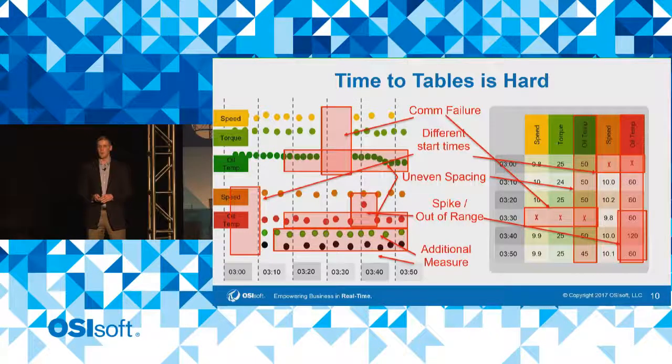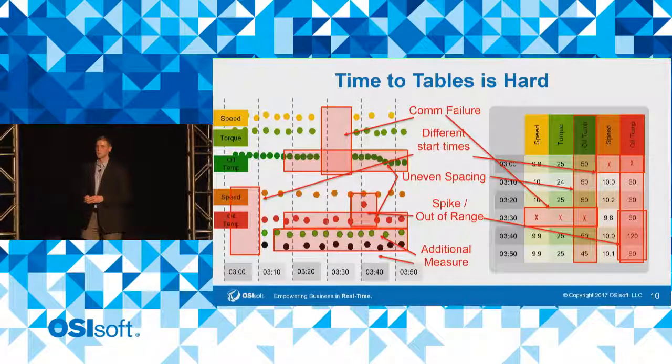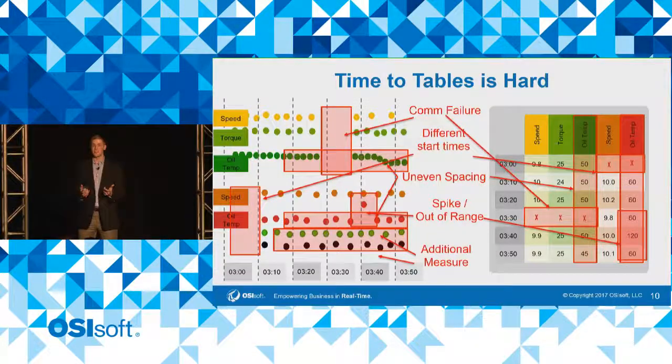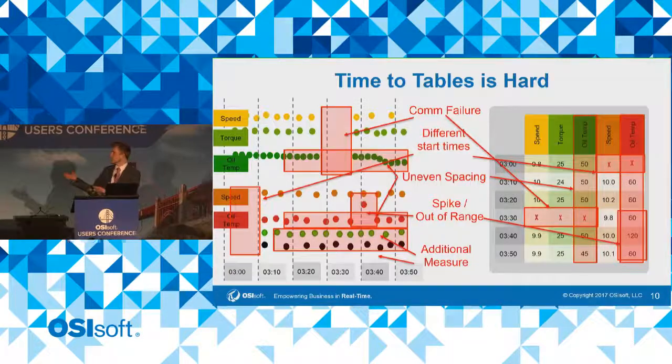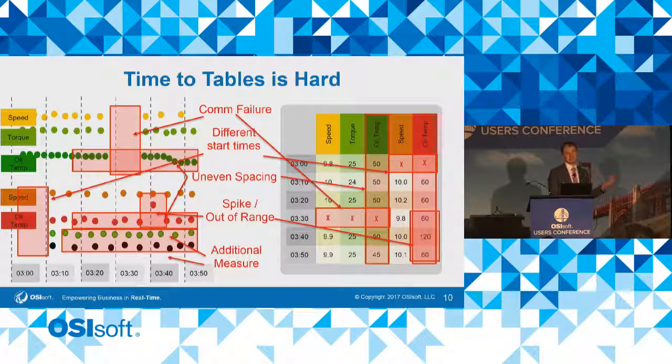Well, luckily, the PI system is really good at handling that time series data on the left-hand side of this display. The PI system is not a relational database, but we've really been built from the ground up to handle time series data streams. We've been designed around that. What I'd say is you could get the job done in a table, but there would be a lot of challenges with it, and you would lose a lot of fidelity of the data that I think you would want to have, or performance would take a hit. That's just what we see all the time, and it's why we built the PI system to be designed around being a time index database at its core and in how it actually stores data.